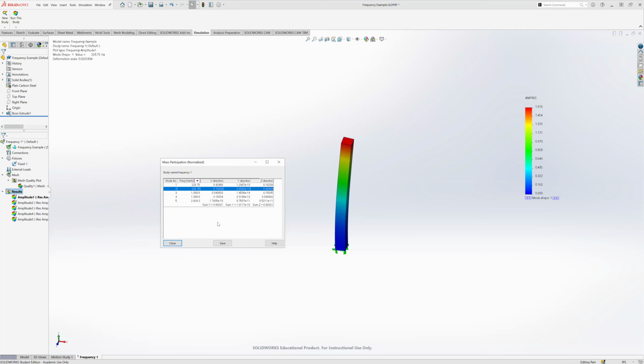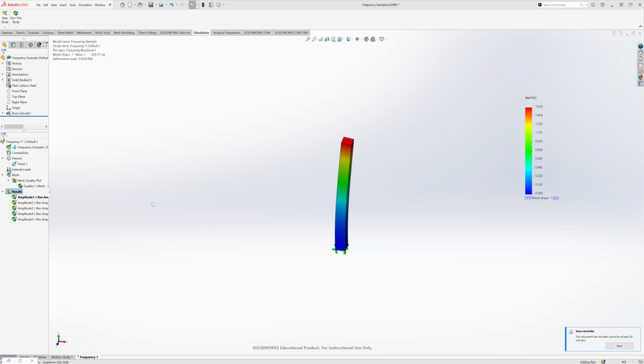Okay. Someone else? In a practical sense, that graph on the side right there, based on those results right now, how would you interpret that from a design standpoint? So, like you said, this was 1 by 1, like a 1 inch by 1 inch. Yeah. So in this case, you would have to stiffen it up, let's try 1.25 or 1.5 inches, and that's where you would just try to slowly work your way up to where the whole part would be blue. Not necessarily in the simulation, but not necessarily.